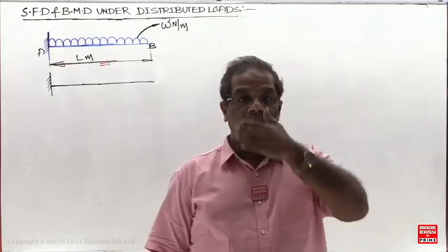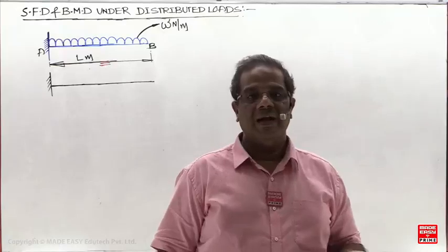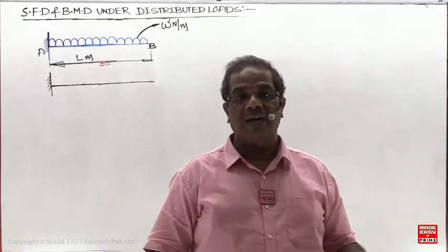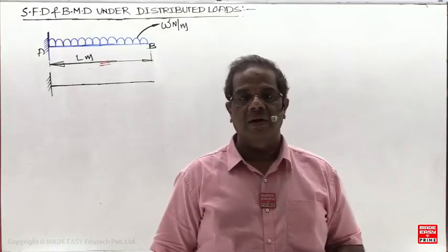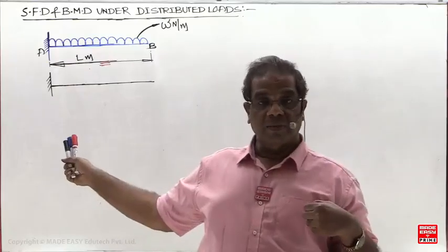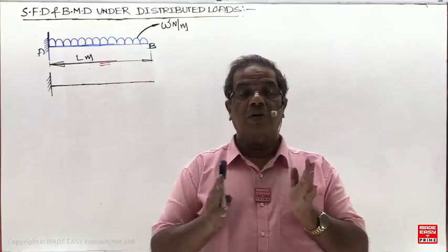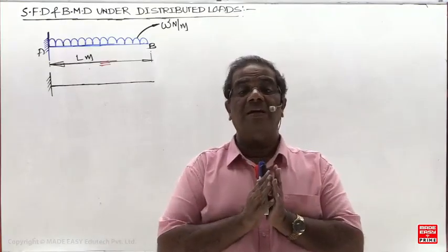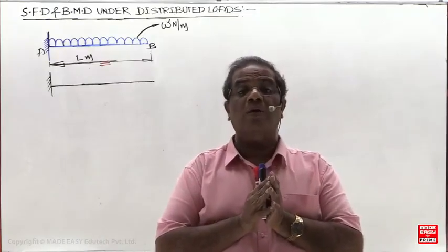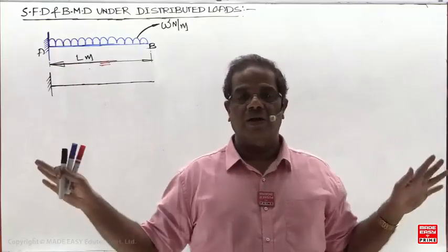Because in the case of constant load, the bending moment varies linearly, so you can use similar triangles. If I use my method, to draw the SFD and BMD under concentrated point load and constant moment, no section is required. Directly you can do it.